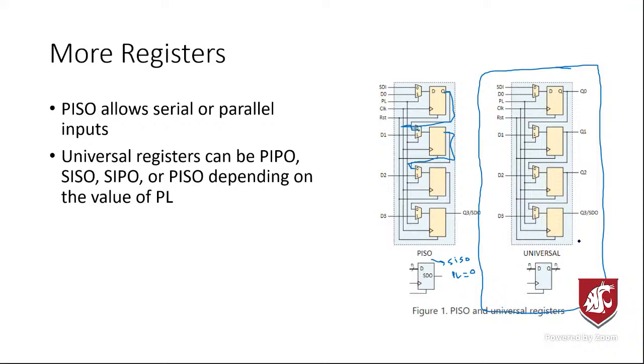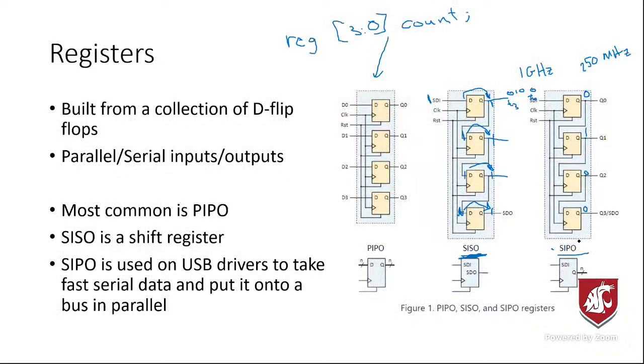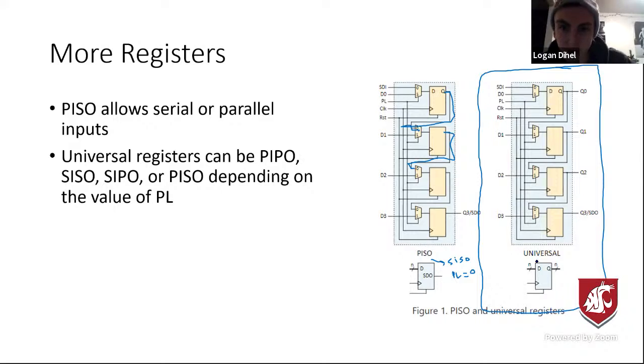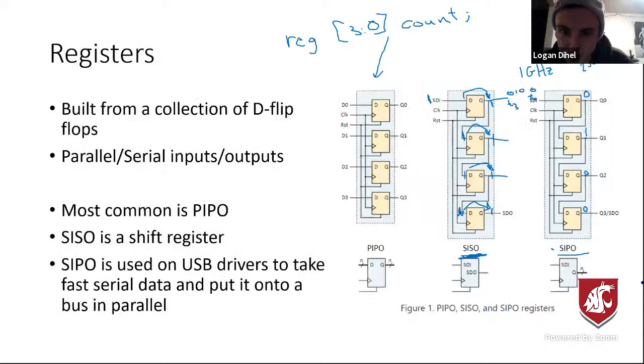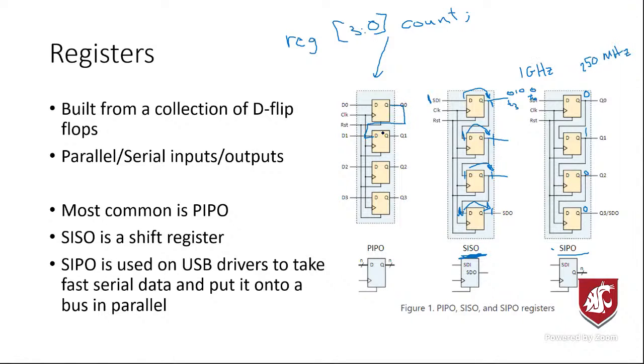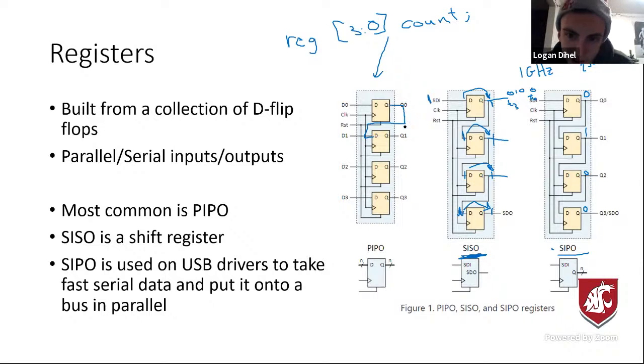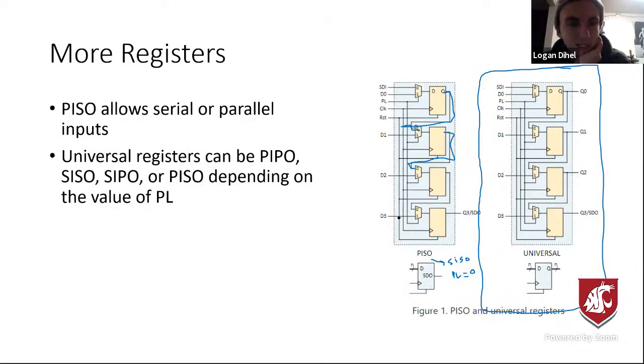So could you use a PIPO like a PISO? Is that the same thing as well? So no, you can't, because you'll see that there's no feed forward loop. With all the serial out ones, you have this kind of weird branching thing, but that doesn't exist in this one. That's actually the only one where that doesn't exist. But yeah, good question.